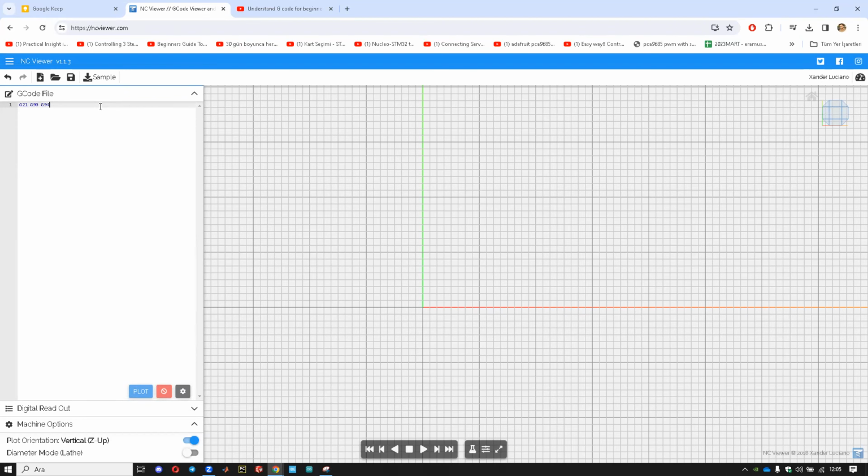It is going to be millimeter per minute, okay? And for millimeter per minute, we have to write G94. So those were our needed modes. After that, I can start to write my actual code, which is for meshing.